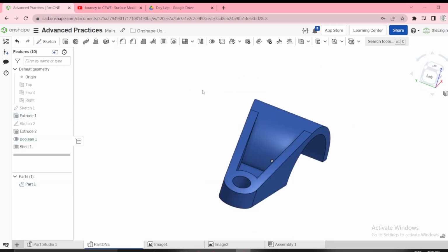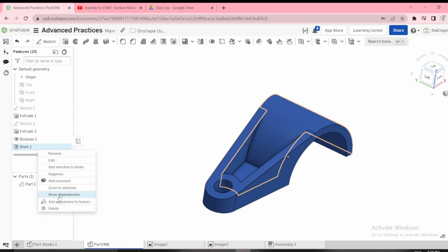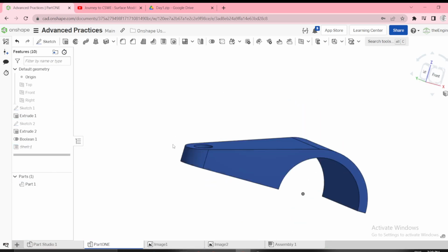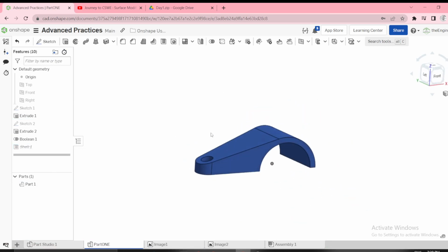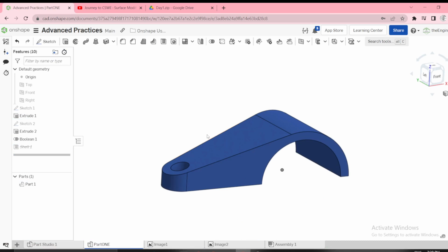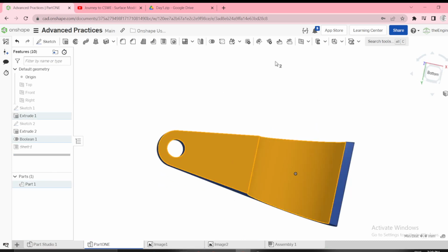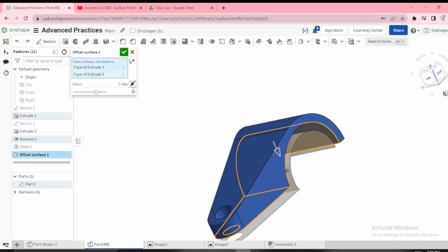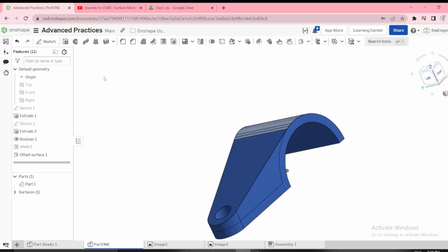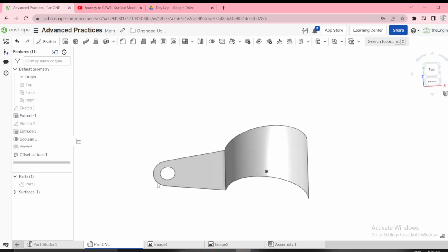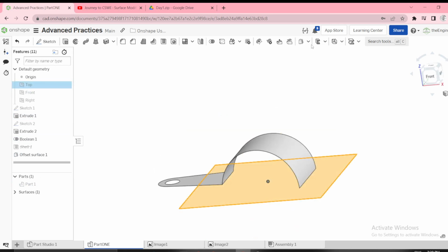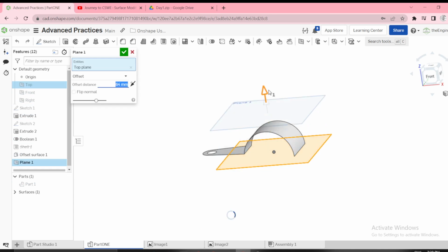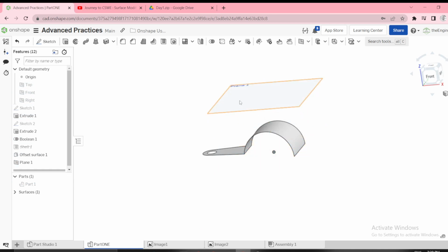Okay. Another way I can do that is a bit complex, but let me illustrate for the purpose of learning. I can always offset these two surfaces. I want to offset by 7 opposite like that. You have the surface now. On the top plane, I can put another plane that is quite high, a little bit offset, maybe there. And I want to sketch onto this plane.